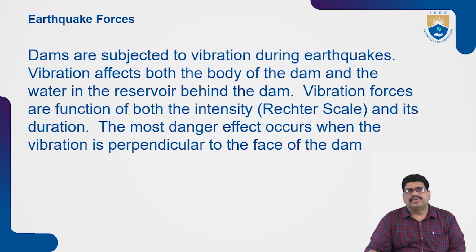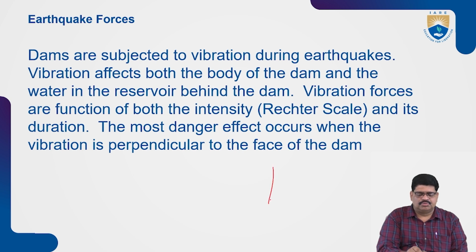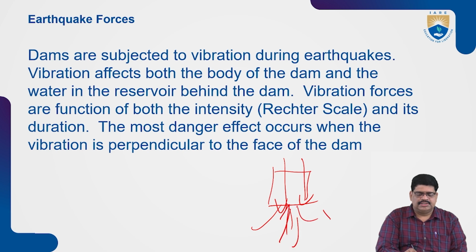Next one is earthquake forces. As we discussed in the previous classes regarding earthquakes, earthquake force is very important. Dams are subjected to vibration during earthquakes, and the forces affect both the body of the dam and the water of the reservoir behind the dam. The vibration forces are a function of both intensity and duration. Most of the dangerous effect of the vibration is perpendicular to the face of the dam. This is the main effect of the earthquake force.